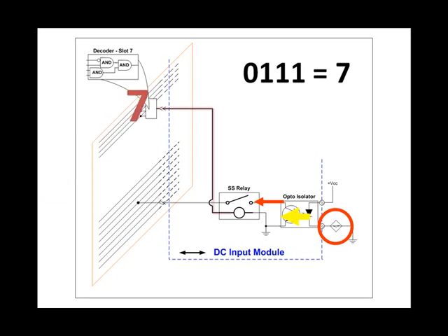This diagram is slightly different than the previous one because it represents the relationship between the backplane and a single output. The previous diagram was for an input circuit. This is an output circuit, one of 16. This is an output, and its state was stored in memory by the rung of logic that controls that output. So in this case, we're not sending something to the controller.